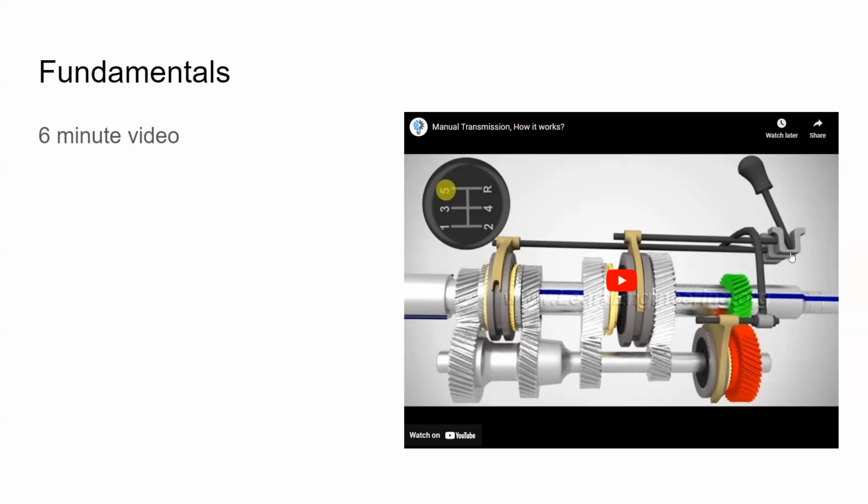three pockets down here. So in your manual transmission, you've got this kind of H pattern for first and second, or above and below each other. And then over a little bit, you have third and fourth. You can kind of see the demonstration up here. So when you're moving the shifter left or right, you're selecting which pocket the end of the shift lever is engaged in. And then when you move it forward or backward, you're moving that particular rail.